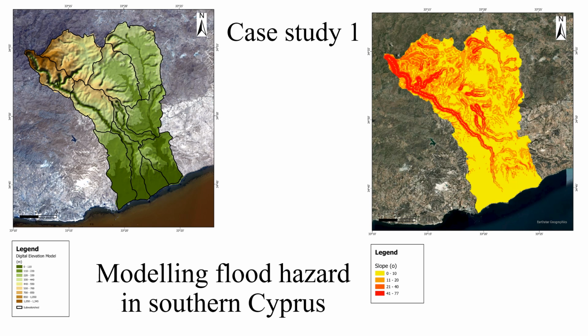Elevation was also one of the most important parameters of our model, and in fact the most important one. As I explained above, increased elevation means higher amounts of rainfall. Thus, as we move downstream, more water is accumulated. In each location, as a total water input, we will always have the rainfall that falls over this location, as well as all the rainfall that has fallen upstream and flows to it. Therefore, as we move downstream, the surface runoff increases, and so does the flood hazard.